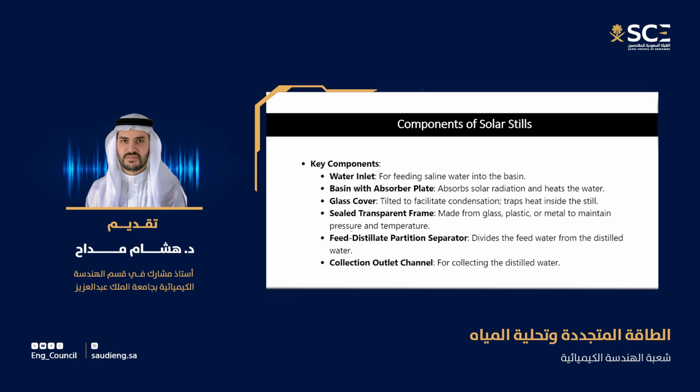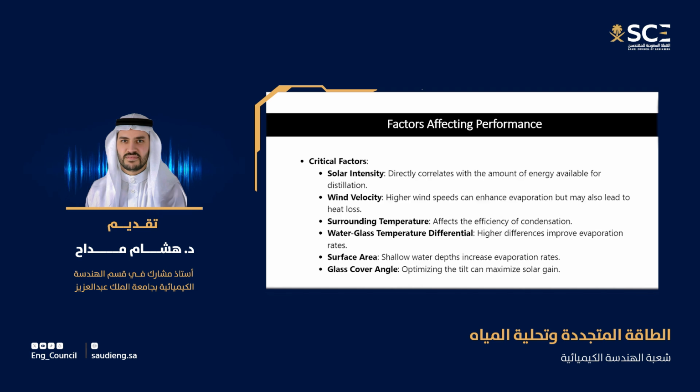The sealant, for example, also the plate itself, the inclination. How much inclination you have, is it 20-degree angle, 10 degree, these are gonna change. These change based on the experiments, but the optimal angle is like 20. Some factors gonna influence your design. What are these factors? Solar energy, how much solar energy you have, do you have wind velocity or no, how much temperature of the atmosphere around you.